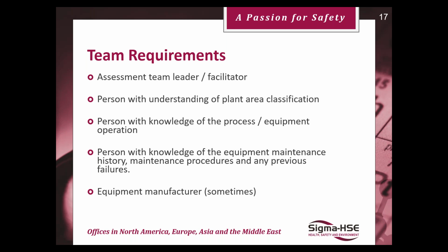The important thing when I undertake NIRAs is this historical experience. In the more complex equipment like your reactors, which handle flammable vapors, I've done jobs where the experience really helps, especially when they want to find out about bearings or if there are any loose bolts, because from experience they considered this, like smoldering, as a potential ignition source. Because you have that experience, you can put that into the risk assessment and then apply the new safeguard, if there is a safeguard, or maybe there isn't a safeguard.